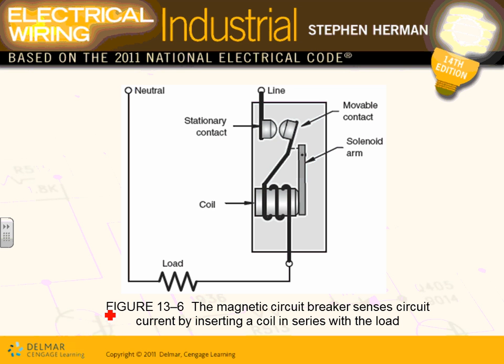Okay, Karen, there's some coil. Here's the magnetic circuit breaker. The way this guy works, if this is a 20 amp, gentlemen, and you have a short circuit right here, a ground fault, going to the ground. So now you're pulling out of a 20 amp, let's just say 300 amps momentarily. Can you guys see that? You're pulling 300 amps. Now the current is going to go through the coils, right? When it goes through the coils, it's going to create a magnetic field that pushes this solenoid arm away and opens the circuit breaker.